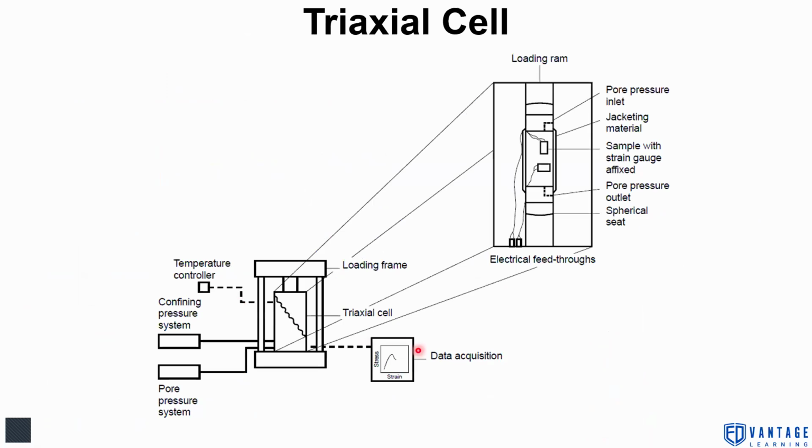Okay. So now, as I was talking about this experiment, our objective is just to see the failure plane, right? So what we generally do is an experiment called a triaxial test. A triaxial cell contains your axial loading frame from the top and confining stress given radially. To understand this properly, let me draw a bedding plane.